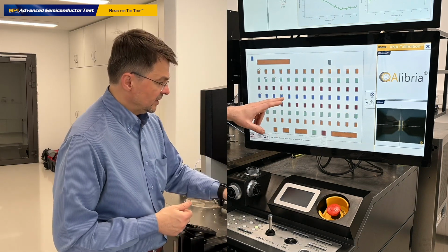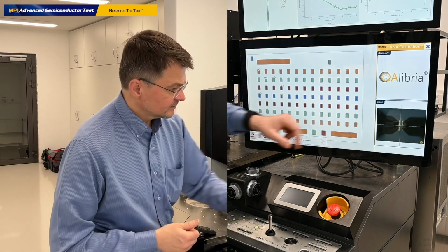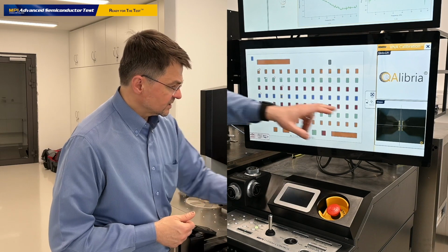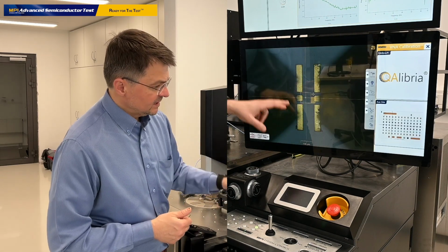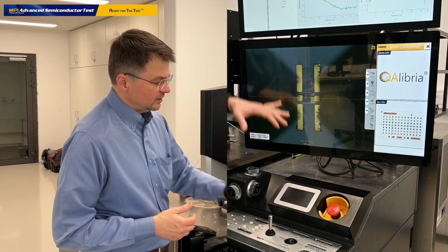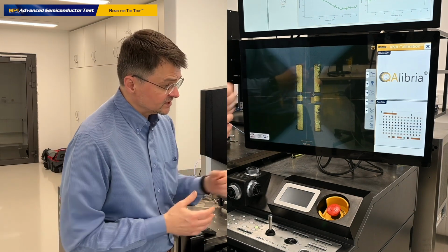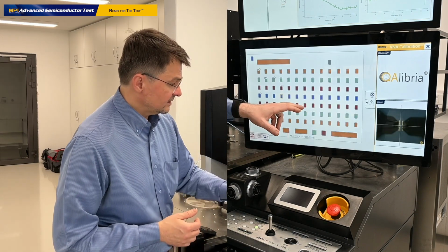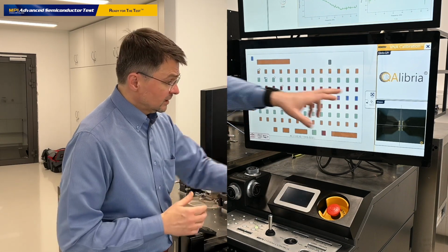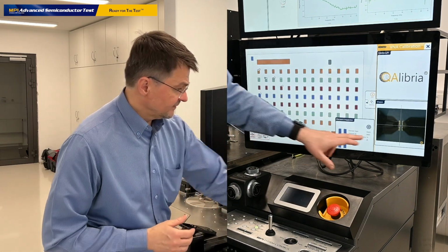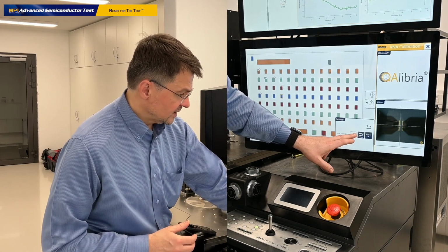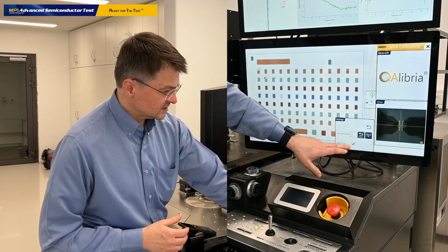So how about the open? This open looks not good. It actually looks like this open experienced some damage here, which means that what I can do here, not to be confused any next time I move to this calibration standard, I would like to set the lifetime of this particular open standard to 0, which means that I cannot use it anymore. It's at the end of its life. So that's the selected standard, and I would like to mark it as a bad standard.